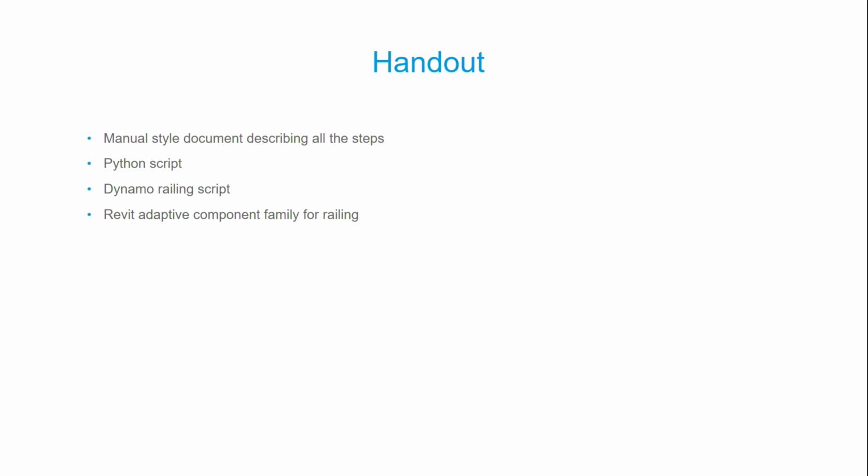Can you send changes to the Revit model back to InfraWorks? The what? Changes in Revit. Yeah, this is what Michael was asking. This is coming a bit later next year. So first, today you can make changes to InfraWorks and push them into Revit. Now we're passing all the property sets to Revit, so those will be exposed. And then we're going to follow up to allow you to make changes there. So whether you make changes in Revit or InfraWorks, it shouldn't matter. The model's always going to be in sync in the middle, right?